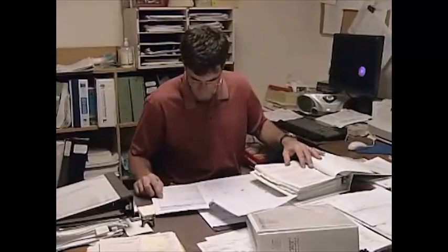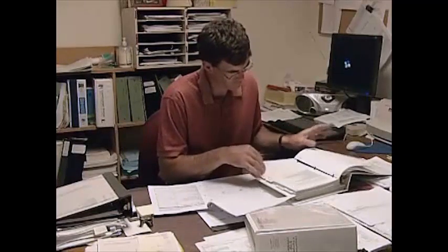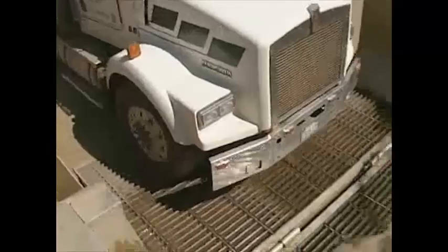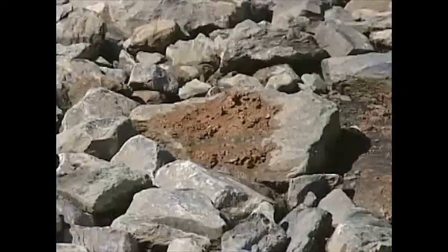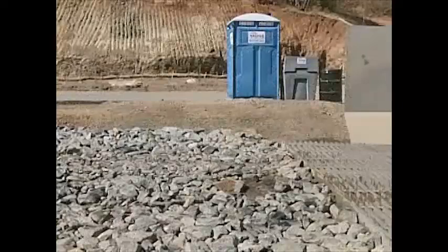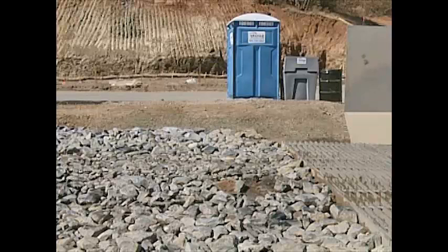If a specific deficiency is found while performing an inspection, ensure that a corrective action is implemented. If the deficiency is a result of an inadequate BMP, other measures may be initiated to resolve the deficiency and ensure contract compliance. Specifically, check to determine whether the tire wash has been constructed properly, whether the coarse aggregate used is approximately 3 to 6 inches in diameter, and if it was placed onto the geotextile fabric at a depth specified in the project special provisions.